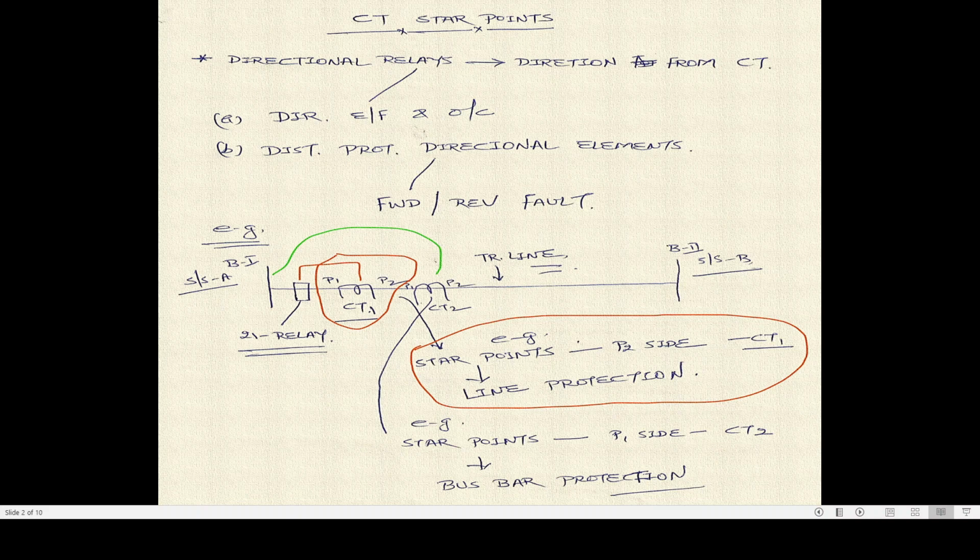And why, when your transmission line is in shutdown condition, and although the complete dia is in closed condition, that means all the three breakers of the 1.5 circuit breaker scheme are in the closed condition, how then the CT currents are distributed, why we get zero current inside our distance protection relay, and what happens when your tie bay is in open condition, what happens when the other side of the dia.